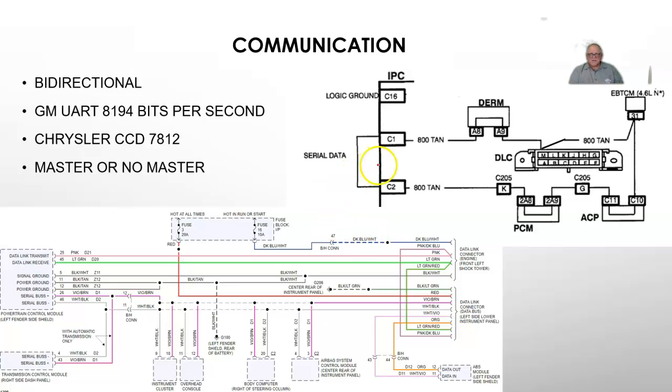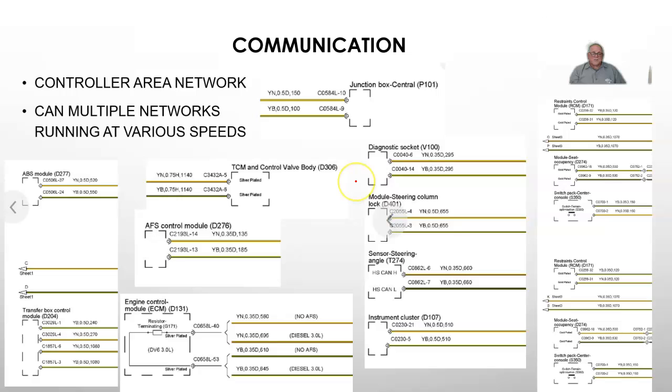By the mid-'80s, all the manufacturers were going with bidirectional communication using various technologies. Bosch came out with what is arguably the best system that's around, called Controller Area Network. On the Controller Area Network, they will come with various speeds. Bosch did something really strange, and that is they gave this technology away. Whoever wants to use it can. Where Bosch makes their money is technical support.